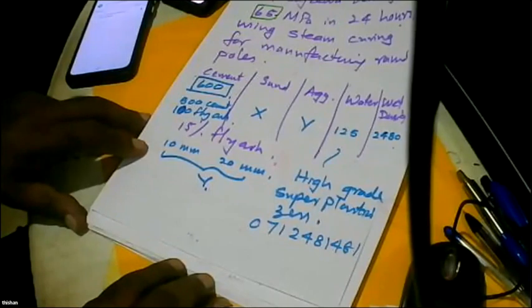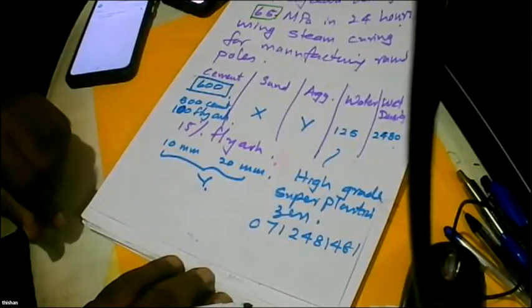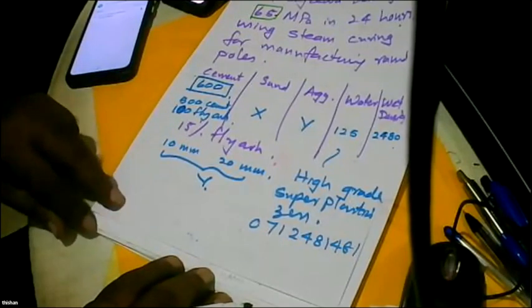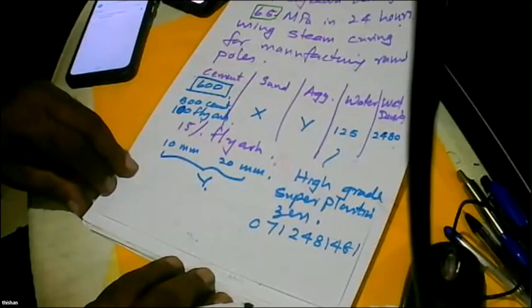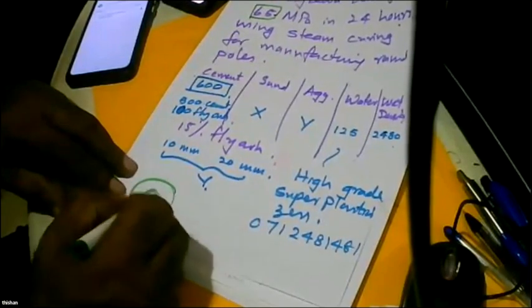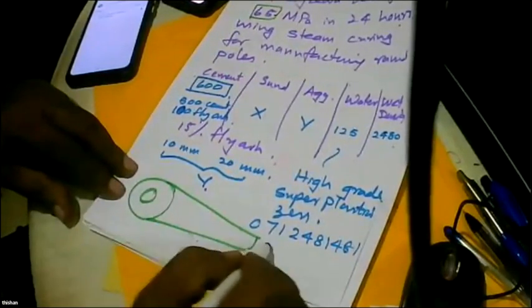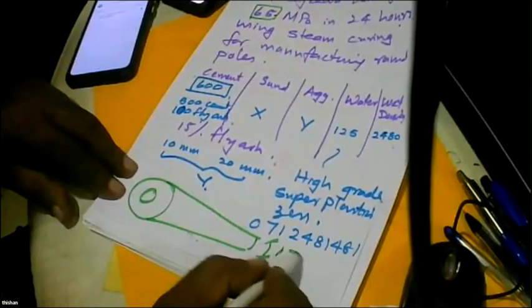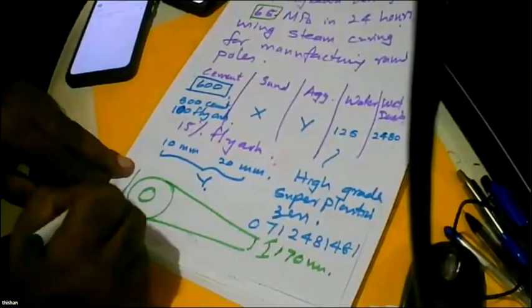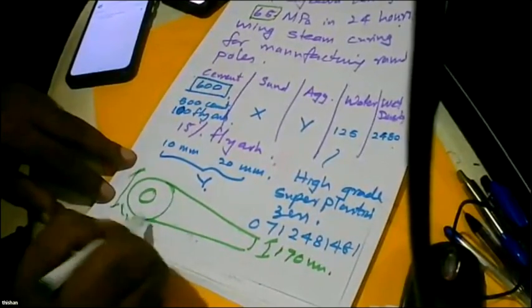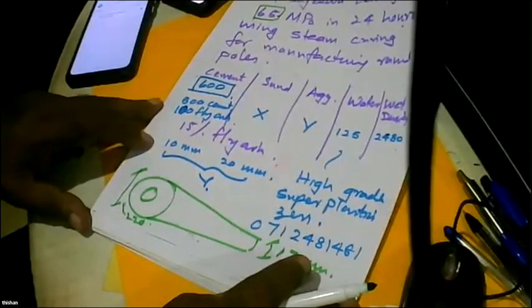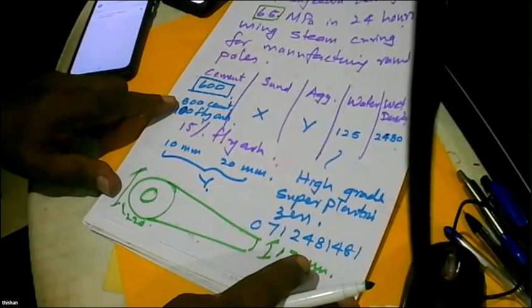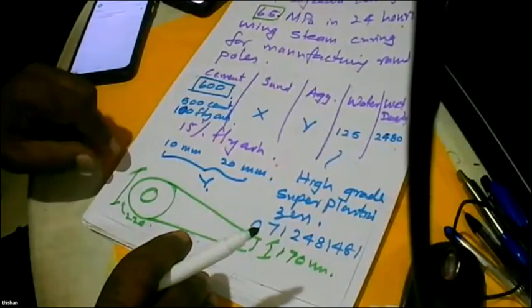So it's good to have something like 600 cementitious material, not cement, but cementitious material. And because these are very small hollow poles, on this side it may be about 170 millimeters, here it may be about 220 millimeters, very small. So you don't have to worry about DEF due to high cement content, but when you are doing the steam curing, you have to control the temperature. Now let's look at what I did.